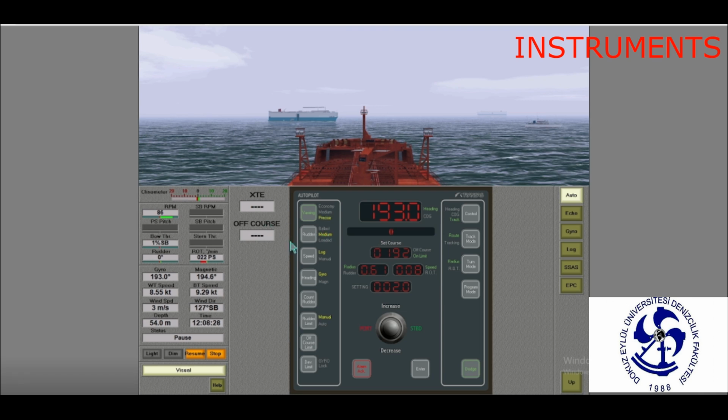Speed. Speed key for setting the ship speed, used for selecting the parameter input mode. Heading. Key for selecting the heading tracing sensor, gyro or magnetic compass. Rudder. Key for setting the coefficient of correspondence between the rudder angle and deviation off course value, used for selecting standard settings.